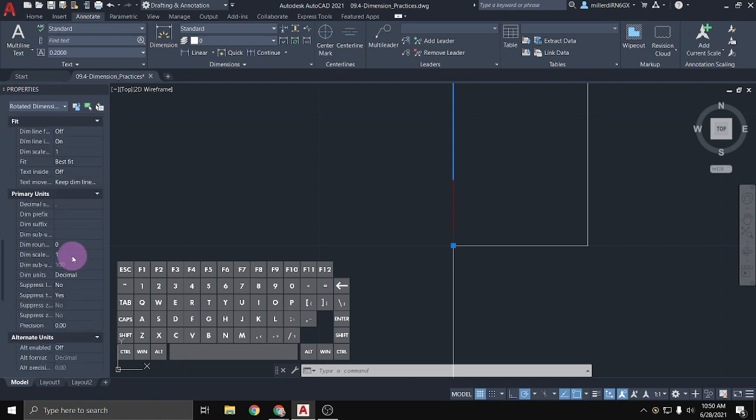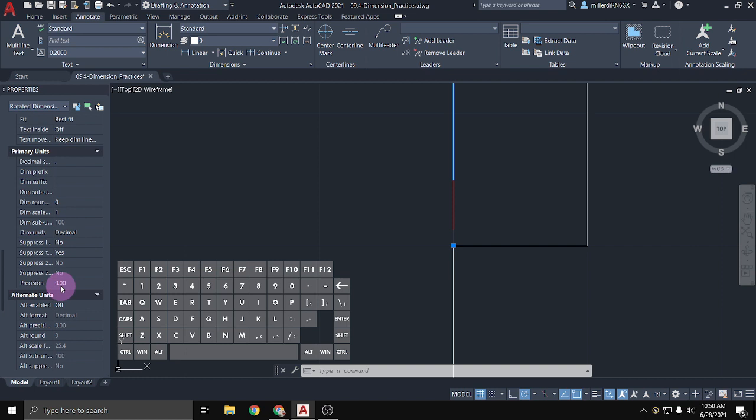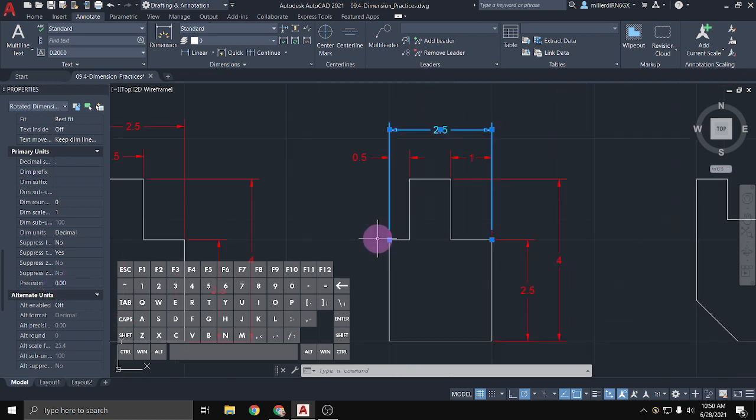Other things I can switch are things like the precision here, so it's going to 2 decimal points, which we're not going to see much of a difference here. But let's say I make it 4 decimal points. If I come here and take this suppressed trailing zeros off, then we can see that it added more numbers to it. So maybe if this was a kind of longer decimal point, and I switch that precision from 2 decimal points to 4, it would then show me more of the number. But in this case, since it was just 2.5, it just gave me some more zeros there.